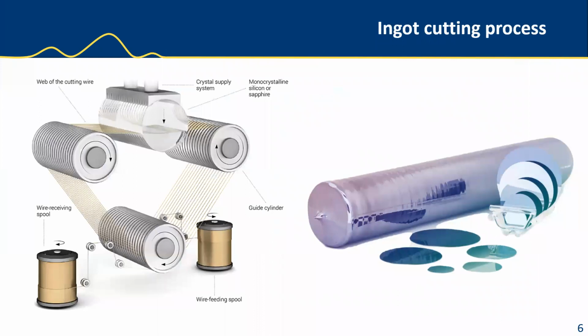A single wire saw cuts the top and bottom, called the crown and tail, off the ingot and then cuts it into sections of a manageable length, which are about 500 millimeters. At this point, a multi-wire saw will cut the sections into wafers. The final process steps in preparing the wafers for use in semiconductors are lapping, polishing, and washing. Layers of material are then applied to the prepared silicon wafer, like a single silicon oxide layer, a silicon nitride layer, and a layer of photoresist coating.